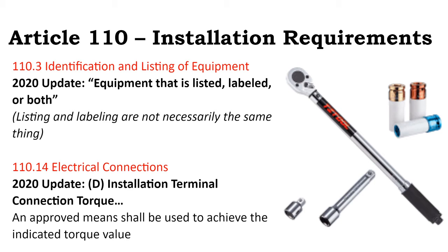There should be a person on site with this torque wrench who knows how to use it and is looking up the torque wrench values and putting it to the adjustable setting and then following alongside them, ensuring that all the values are tightened to spec but not over tightened.